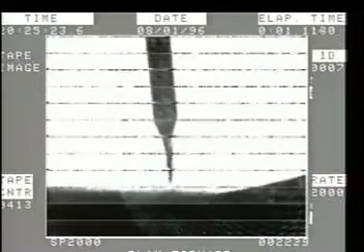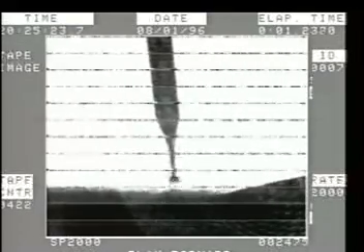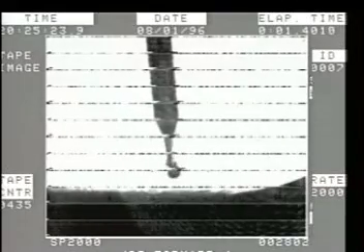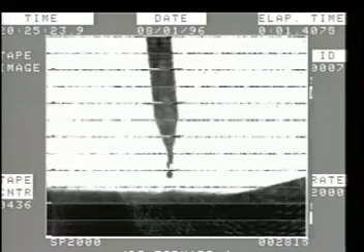The spray arc process has a very controlled, stable arc. There's little spatter, minimal shorting. Molten metal streams from the electrode end. The magnetic field from the arc surrounds the wire. The high magnetic force from that field pinches the wire down at the end. Molten droplets stream through the arc to the workpiece.